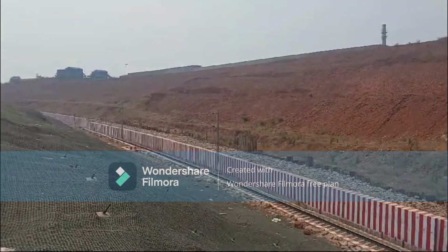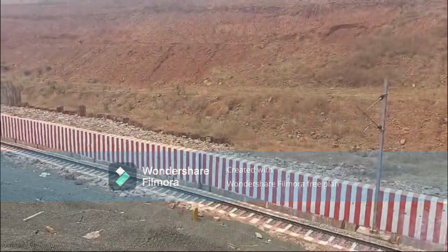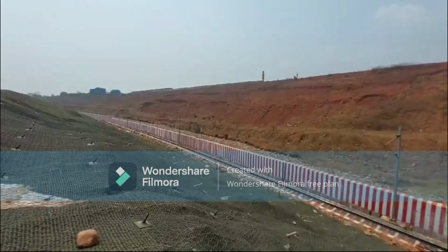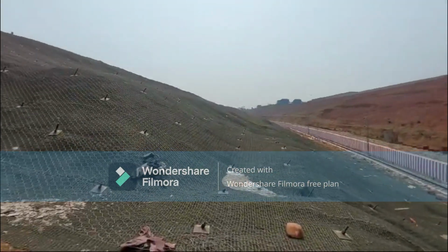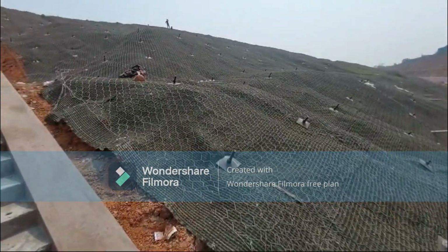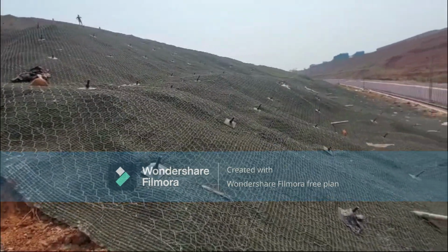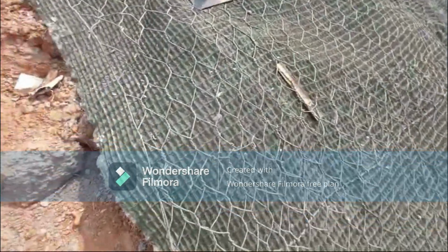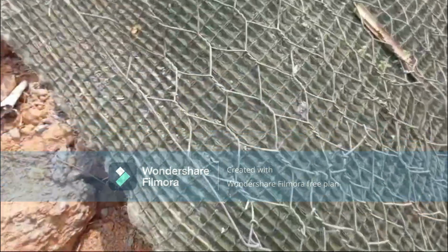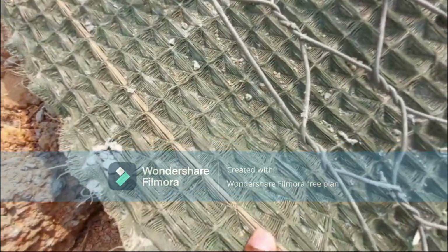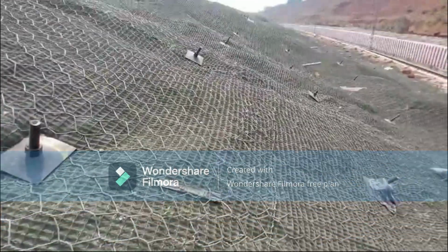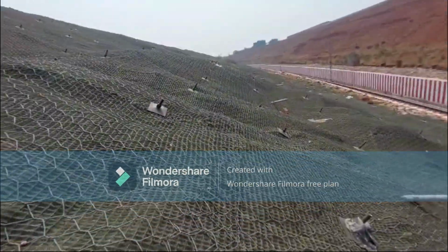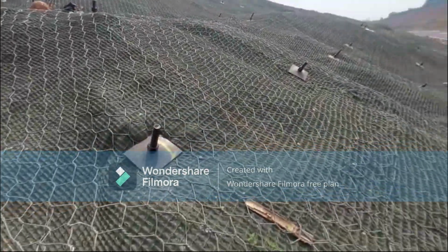And on the opposite side we can see here the collapsed slope. This slope is under testing. This is a steep slope, and this side, the left side, you can say is a gentle slope. It can be stable without any wall, and they have provided the geomat. You can see their design, and also geonet provided with the mat, and they are stitched with the soil nailing.